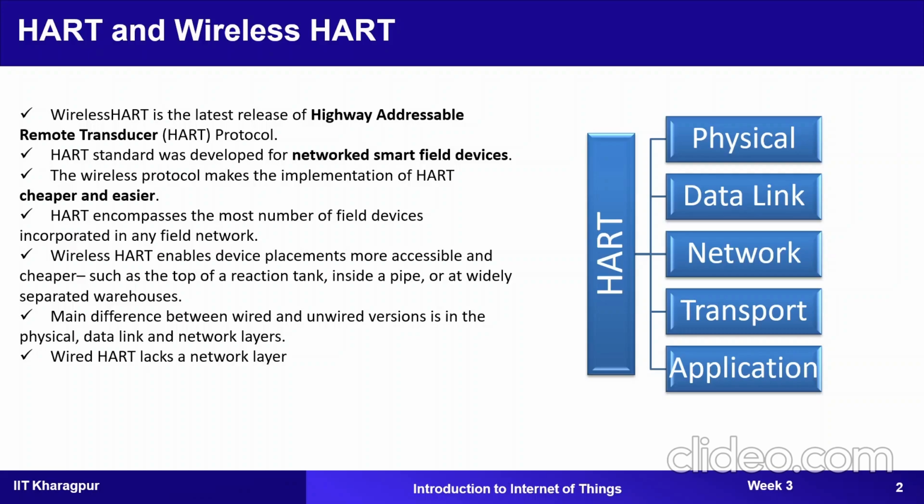Now the WirelessHART network manager. This network manager supervises each node present in the network and guides those nodes on when to send the data, and where exactly to send the data. So this helps in order to avoid the collisions, and also helps in the